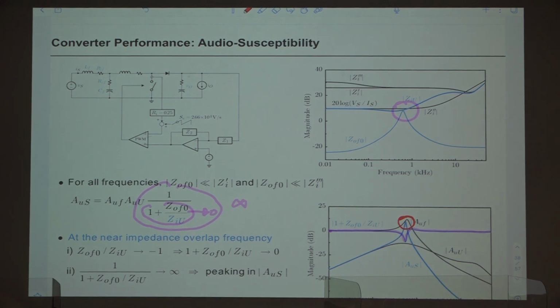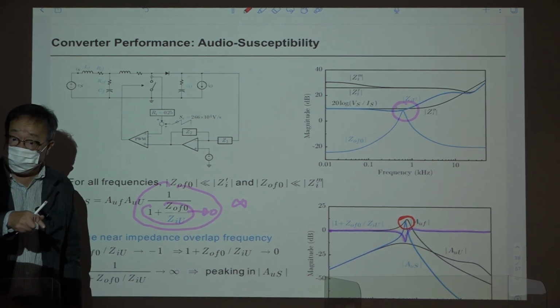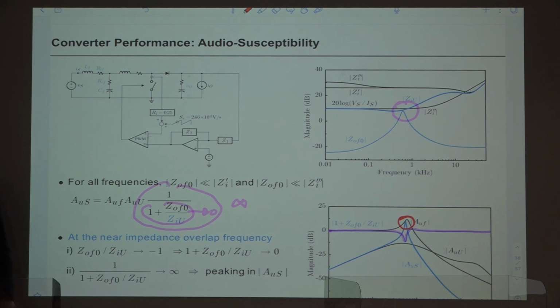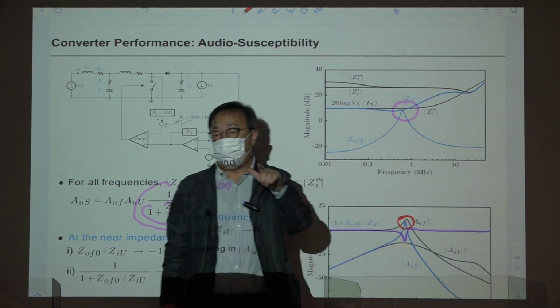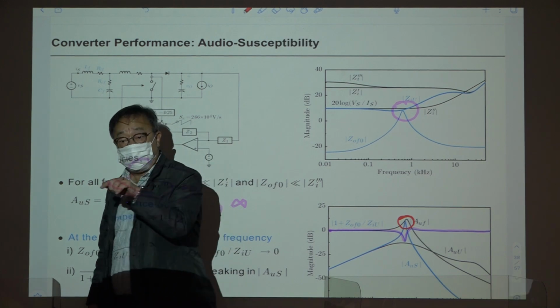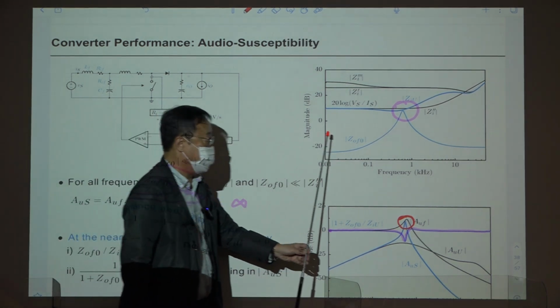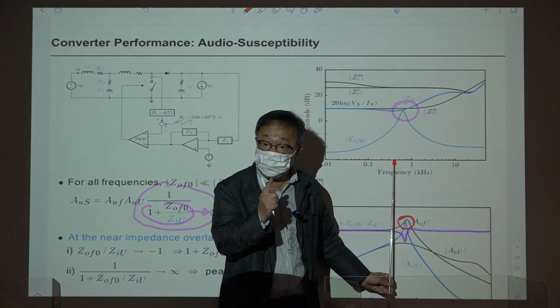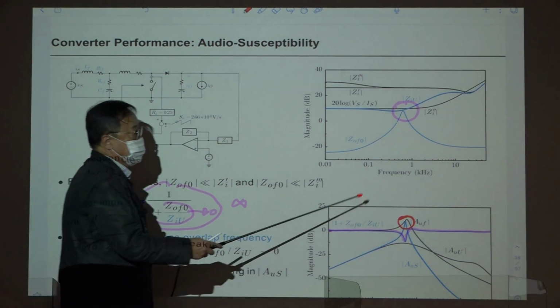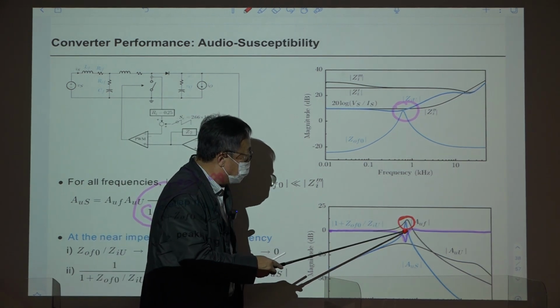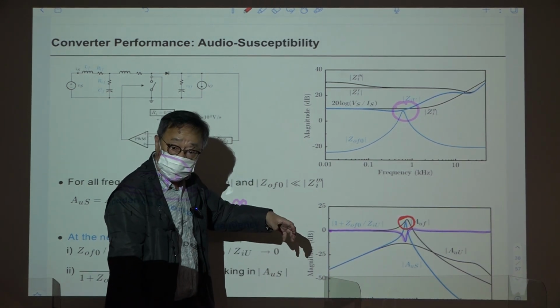Okay. So what is the problem with this peaking? This peaking will generate some very oscillatory behavior in the transient response. For the case of step input response, if you simulate or evaluate step input response, this will be converted into underdamped oscillation, and will produce oscillation at the frequency of this peaking. Right? That is one case. And another one is if there is some noise falling in this frequency range, then the noise, sinusoidal noise, will be amplified.